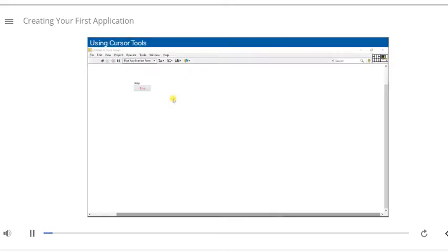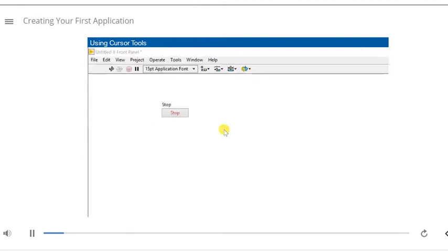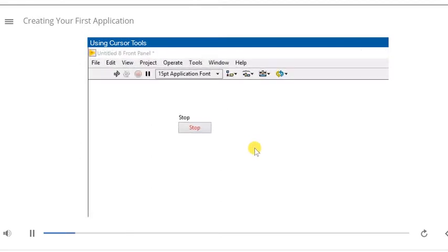When you develop a VI, the position of your mouse cursor on objects in the window determines which tool is active. For example, to operate on a control, like changing a button value, you want to move the mouse cursor near the middle of the control until the mouse cursor appears. When you click, you can operate on the control. To change text, move your mouse cursor over the text until the text cursor appears. Now when you click, you can modify the text.